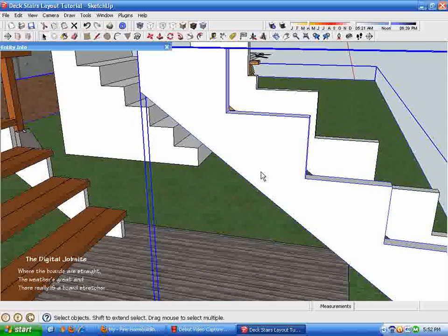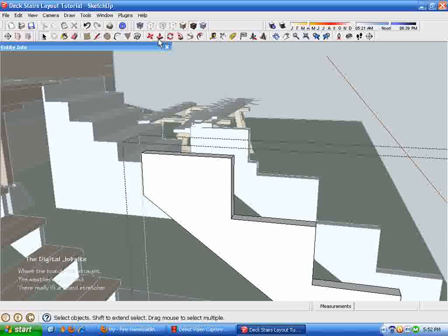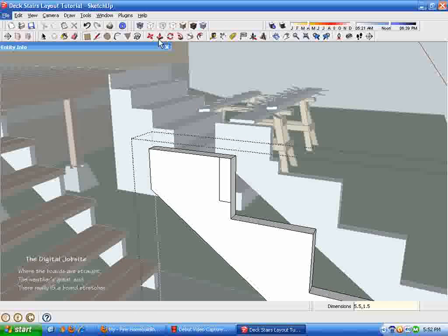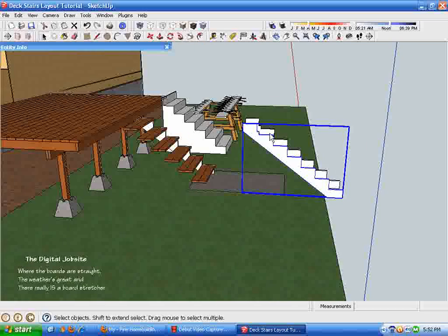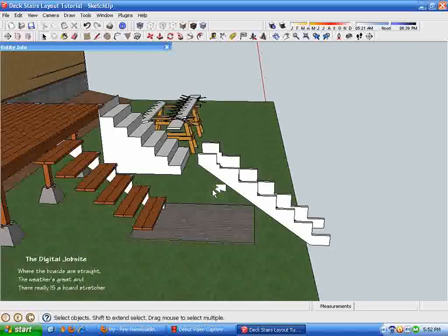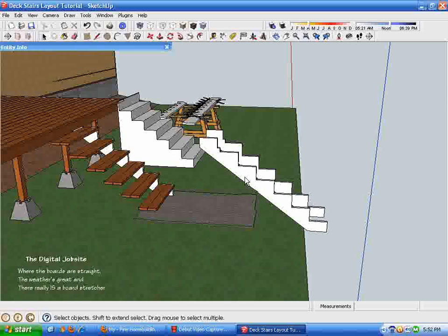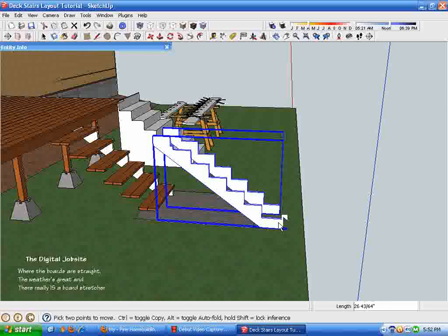So I'm just going to draw a rectangle on here, and it's going to be 5.5 comma 1.5. Puts that little rectangle on there, and then we'll just push it out of the way. And now you can see that both of the stringers have that notch in them. Put them back where they came from at 100 inches. You can see how they fit.